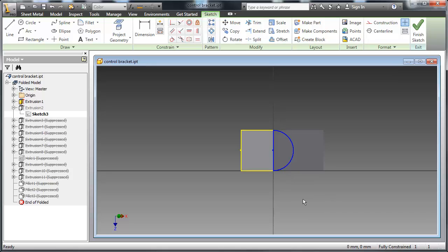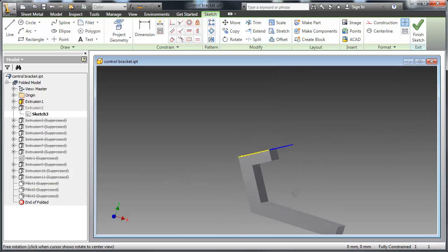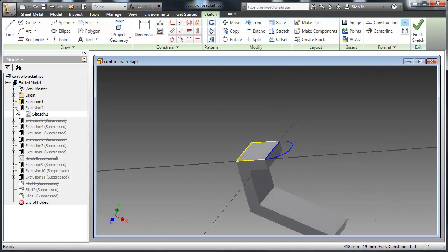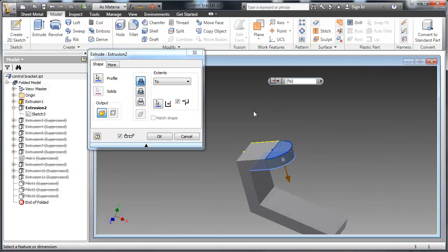The next thing that was created was this sketch to create this curvature on the top here. Notice there are no dimensions. I made use of the existing thickness of the geometry to attach the arc to create this extrusion. Then the piece was extruded using this value and using these options here.